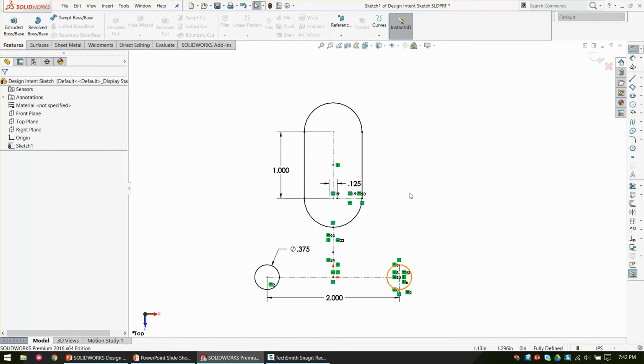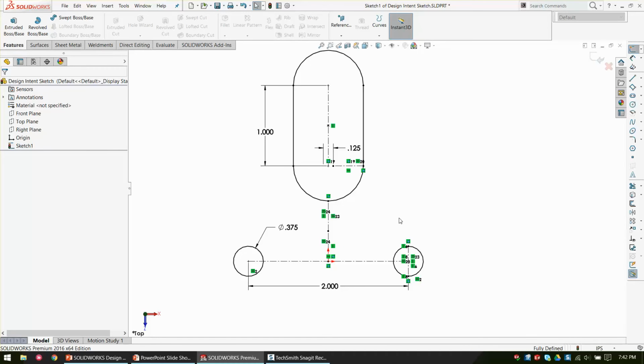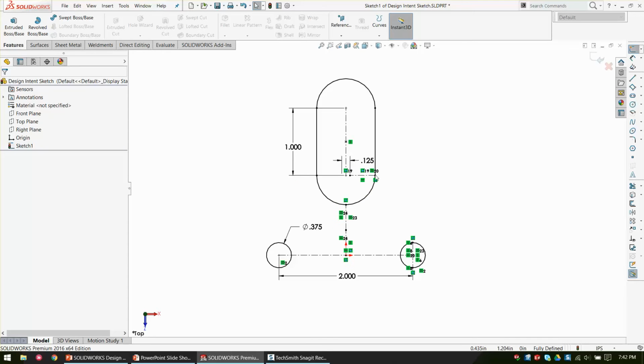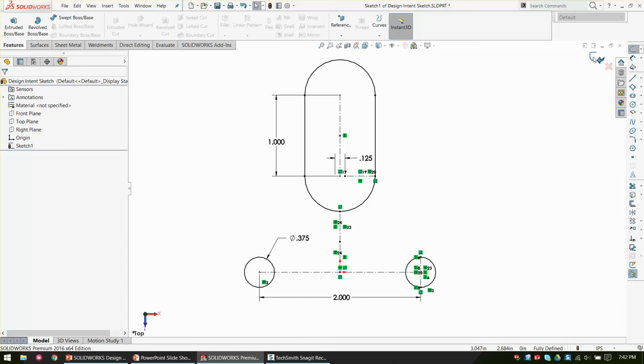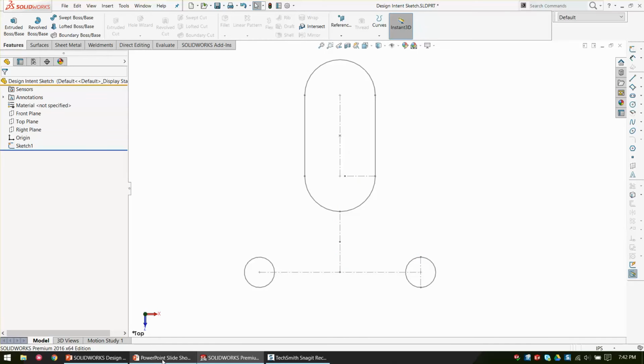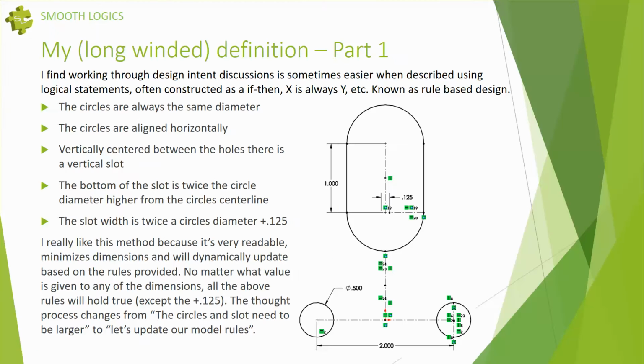So this is kind of an arbitrary example. I was trying to see how much I could fit in here in one little thing. This is not practical, I grant. And most of this discussion is not going to be go home and be super practical. We're very theoretical here as far as what we could accomplish with the tool of SOLIDWORKS. I think a simple way of saying it is to always pick relations over dimensions when you can. If you go back and change the hole, you would have to change it twice. Just use relations when you can.